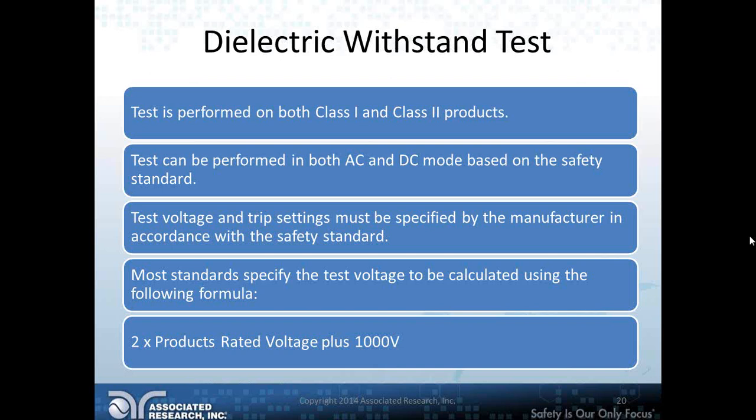Although most insulation resistance testers have a variable output voltage, if you go by the standards, the test is usually specified to be performed at 500 or 1000 volts. And although the insulation resistance test is related to a high pot test, this test provides more information about the device being tested, which can be useful in certain applications.